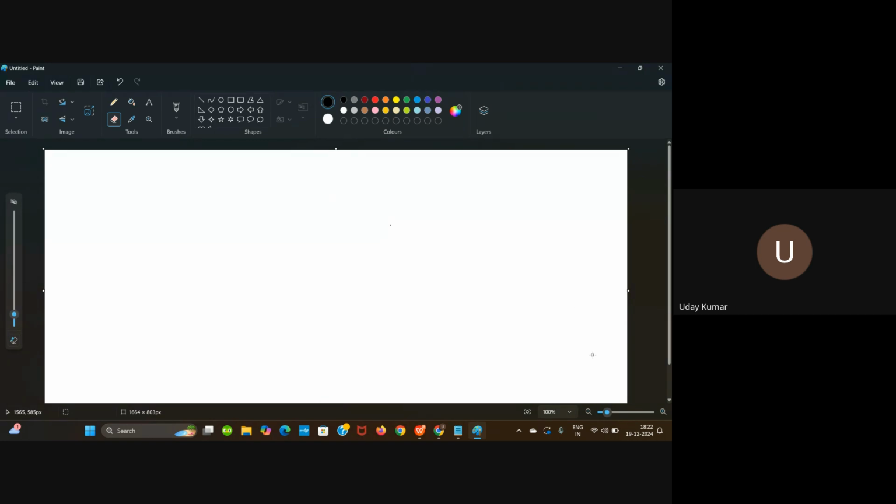So basically, we have an RTL which implements the logic, and we verified it using design verification. Now we want to realize the hardware. To realize a hardware, we also have a modeling called the gate level model.